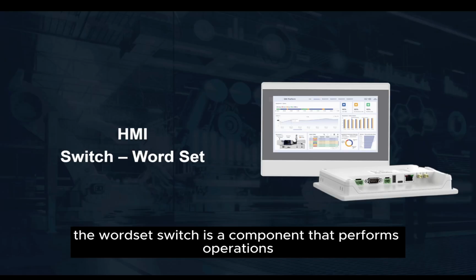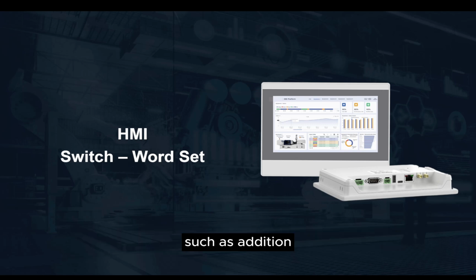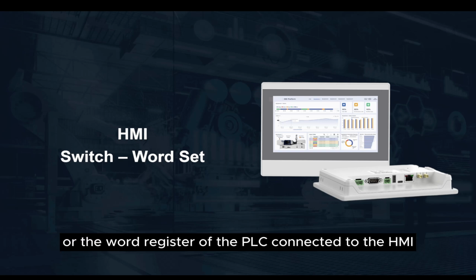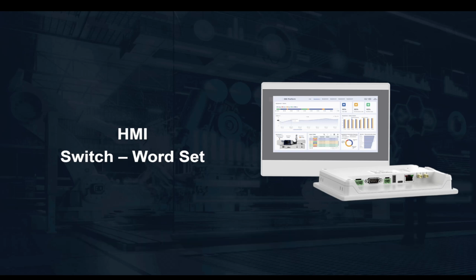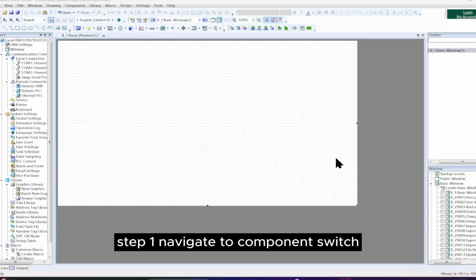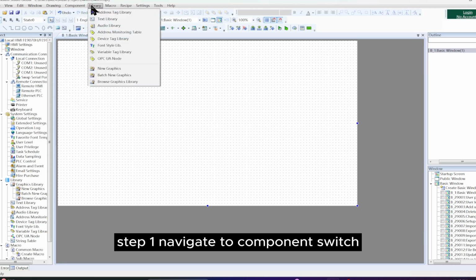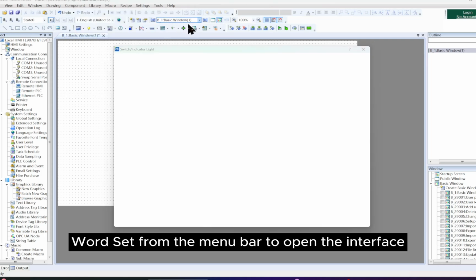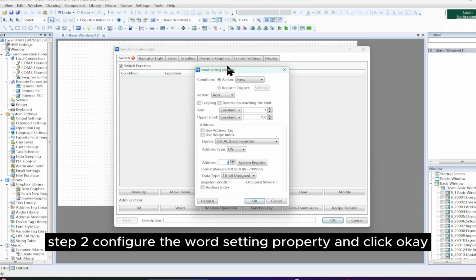The word set switch is a component that performs operations, such as addition, on the value of the internal word register of the HMI or the word register of the PLC connected to the HMI. Here's how you can create a word set switch. Step 1. Navigate to Component, Switch, Word Set from the menu bar to open the interface. Step 2. Configure the word setting property and click OK.